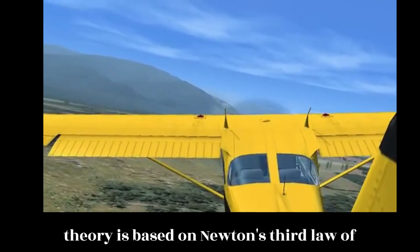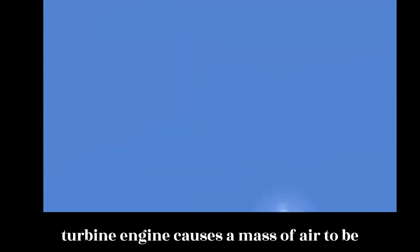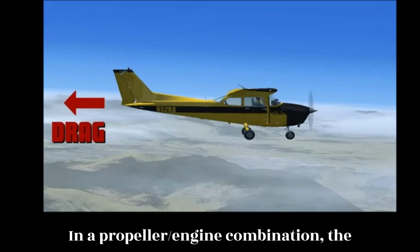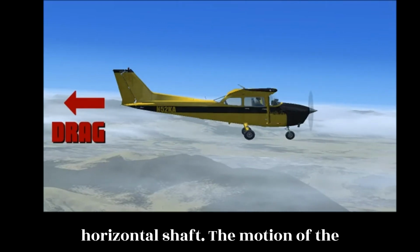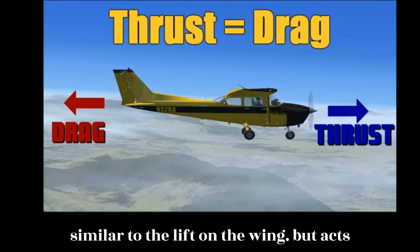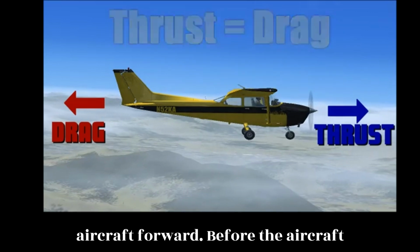Jet propulsion theory is based on Newton's third law of motion. The turbine engine causes a mass of air to be moved backward at high velocity, causing a reaction that moves the aircraft forward. In a propeller/engine combination, the propeller is actually two or more revolving airfoils mounted on a horizontal shaft. The motion of the blades through the air produces lift similar to the lift on the wing, but acts in a horizontal direction, pulling the aircraft forward.